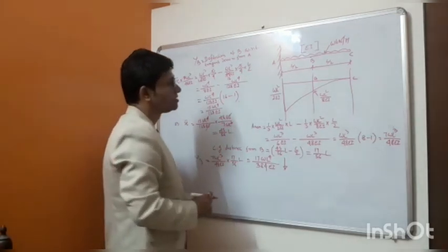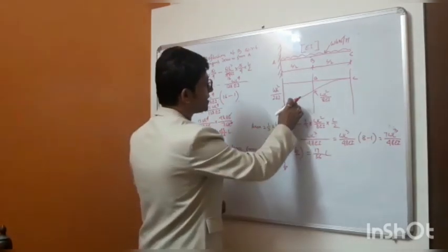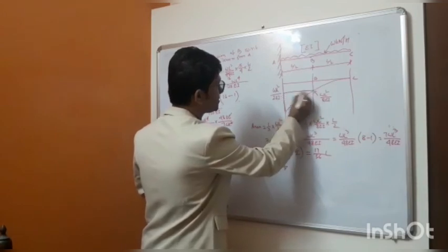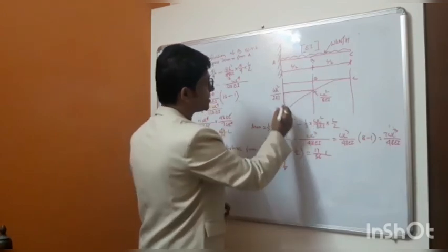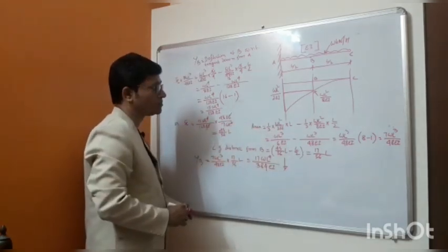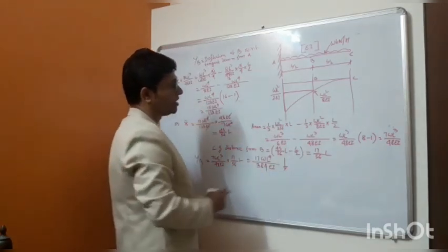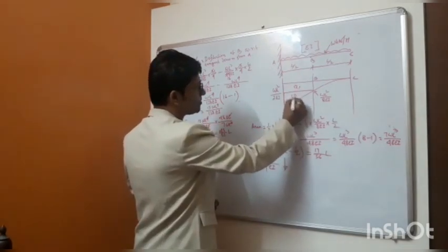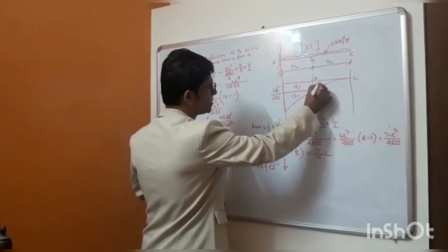Remember one thing, it is never like this that you will just segregate this in the similar way we have done for the point load. You deal with a cantilever with a point load and we will consider this as a rectangle and this as a parabolic curve. We'll take this as another parabolic curve.